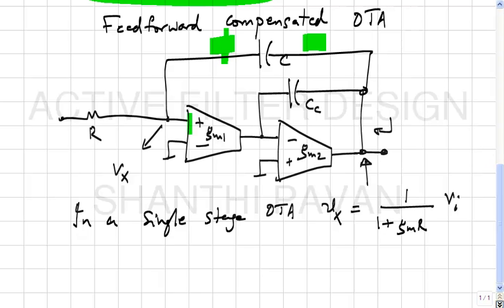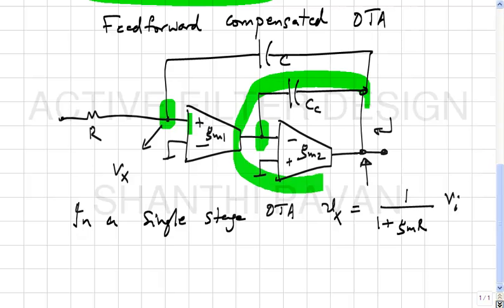So, to get some intuition about what is happening, let us make a few assumptions. One, if we are doing a decent enough job, even if this is not 0, this must be close to 0, correct? This is just to give you first order behavior, what to expect type of analysis. Similarly, if GM2 is large, what can you expect about that node voltage? This is nothing but a current controlled voltage source.